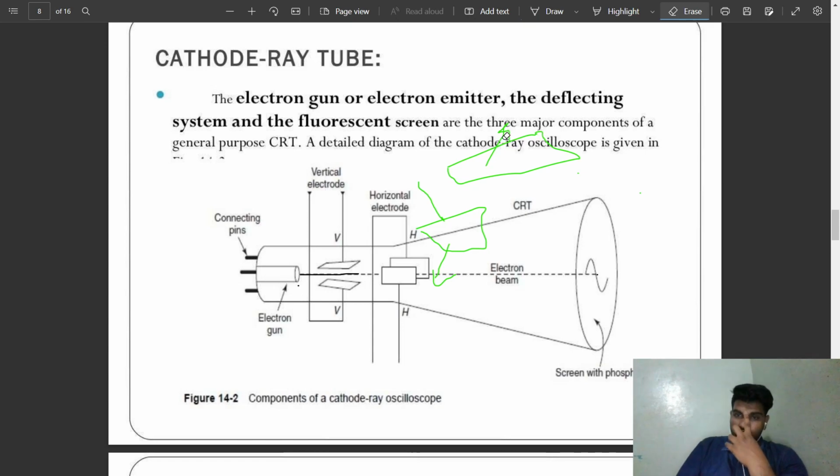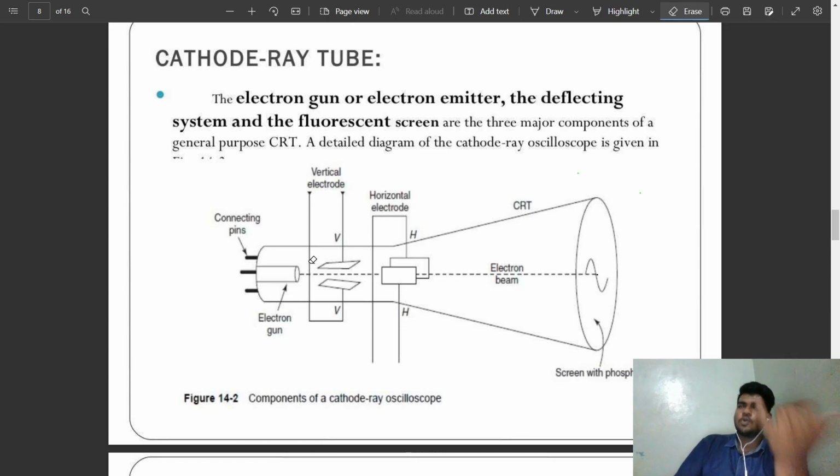You get it, right? And this is the function of a cathode ray tube, exactly how it is, and the screen is made of phosphor. So H is a horizontal electrode. These are electrodes, and there will be pre-acceleration electrodes, a post-acceleration electrode, and then a focus electrode. The post-acceleration and pre-acceleration electrodes have far higher values. Okay, so keep that in mind.